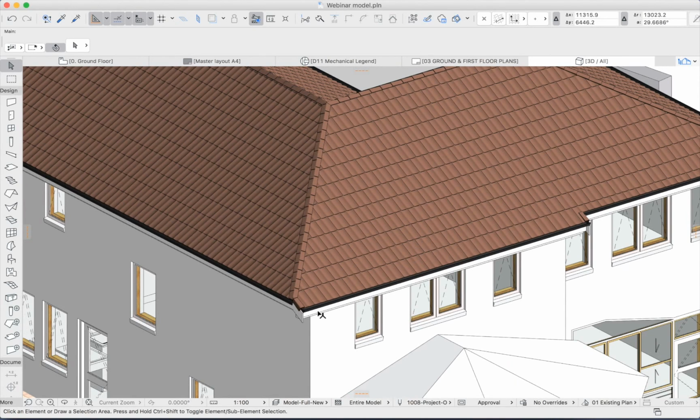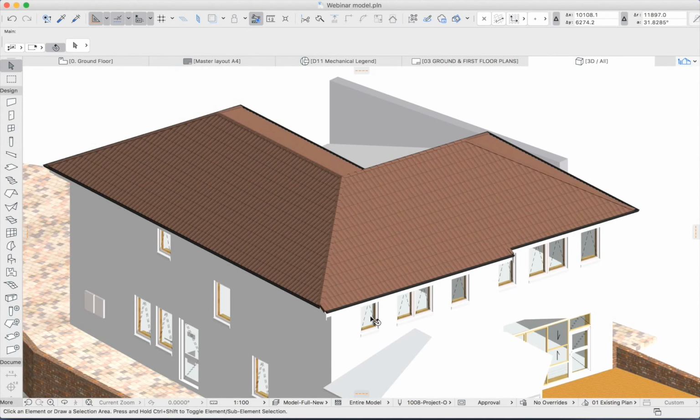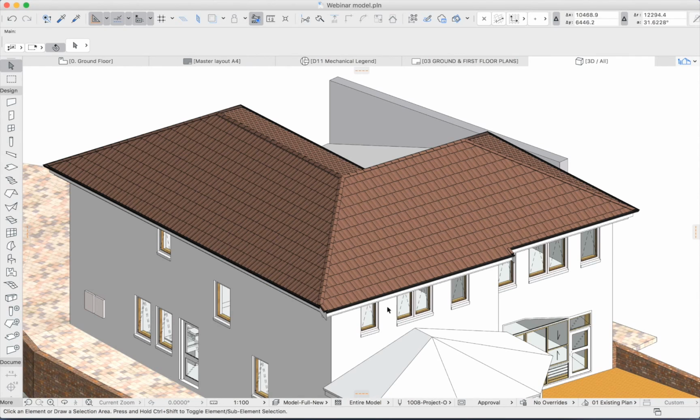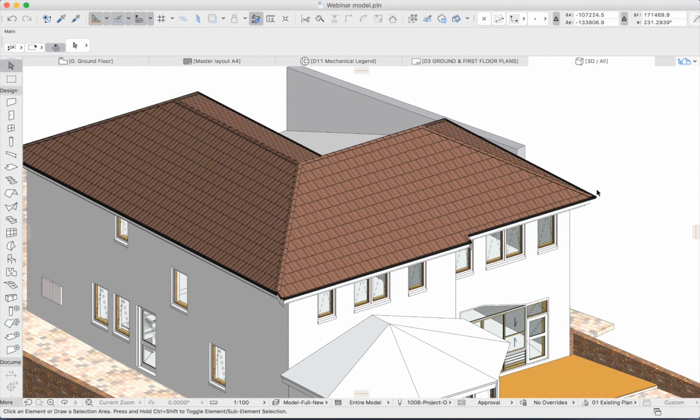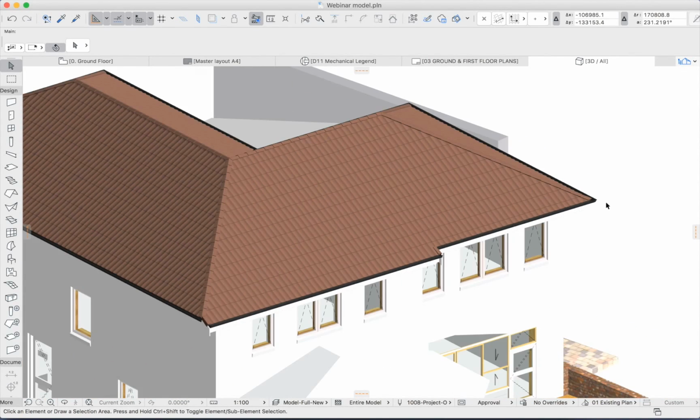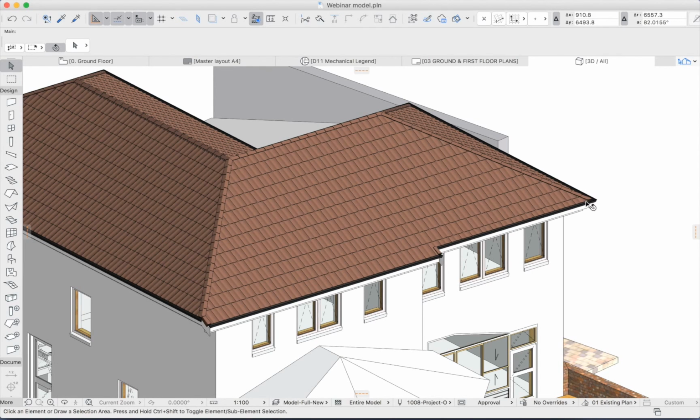And we can see fascias and barges and gutters run around the perimeter. Now you might notice there's one thing missing, the downpipes. The tool doesn't really understand where these should be placed, so it's up to me to indicate where I'd like them, but it uses the settings that I entered earlier.